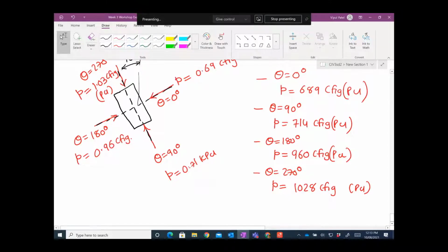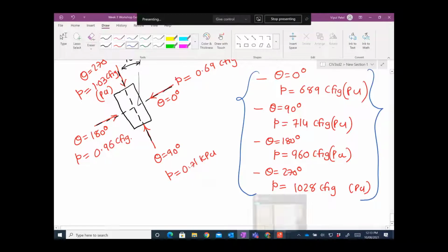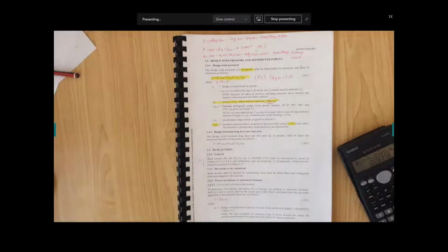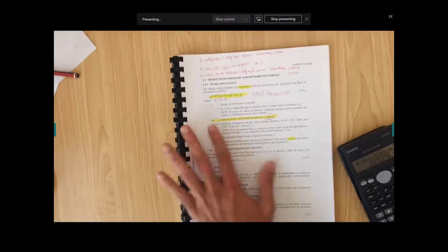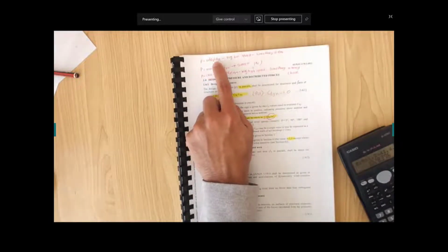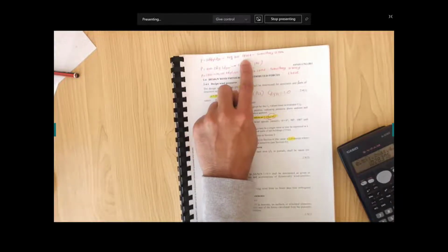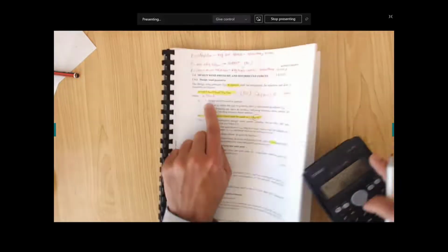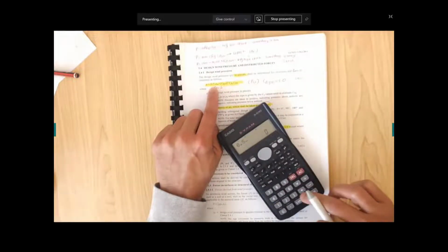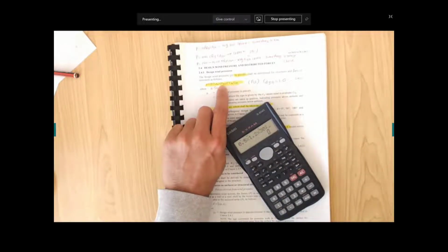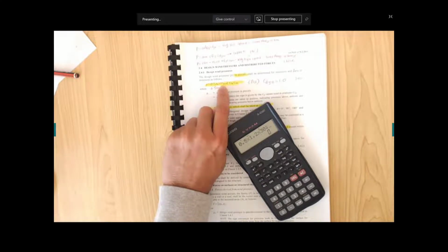Now I have to give you one important note here. When you stop here, you stop here and check it. What check you need to make? When you get the pressure, say 50, this is very low, because as I mentioned, you have this 0.5 times 1.2 times 30. Where is 30 coming from? Regardless of your structures, you cannot use less than 30.